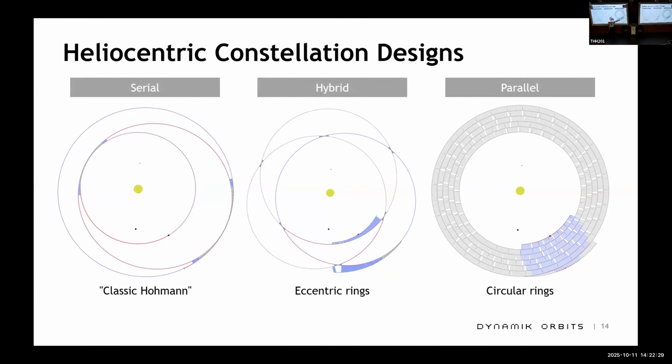And this is parallel data flow, where it still spreads out like that, but then there's 2 big rivers divided into smaller streams, and you take the sum of all the streams all around, even if they're low speed. So this was 500 megabits per second between one satellite and the next. This might be just 2 megabits per second, but you have 300 satellites doing this. So if you have 500 satellites doing 2 megabits per second, then you get to 1 gigabit per second.